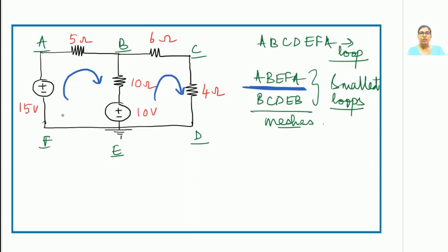Next you have to write the KVL. What is the approach? Always start writing your equation in the clockwise manner. Try to write your equations from this corner onwards and take a loop which starts like this, goes through the resistances, the voltage sources, and back again to the starting point. This is the standard concept that I refer to while solving circuits.